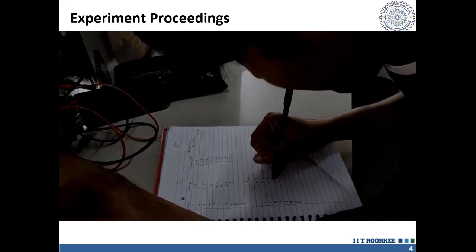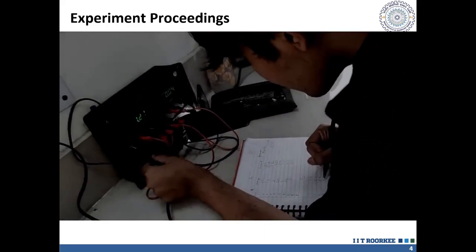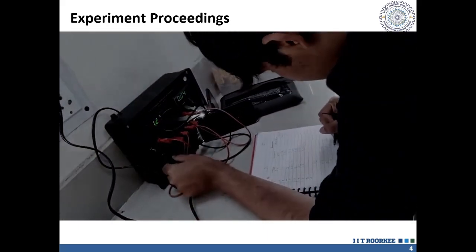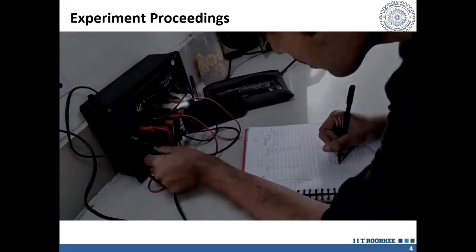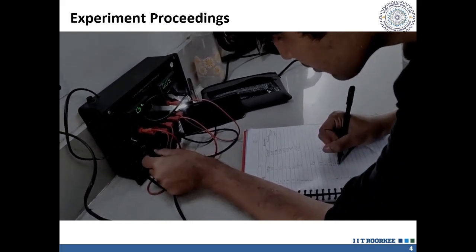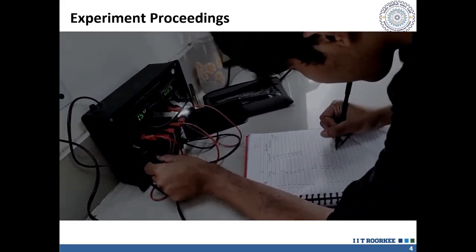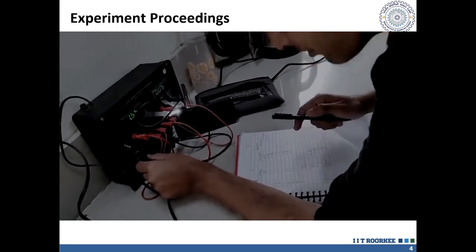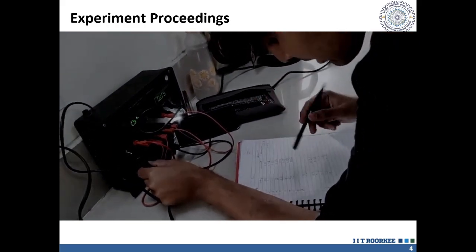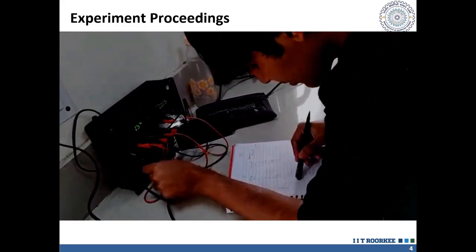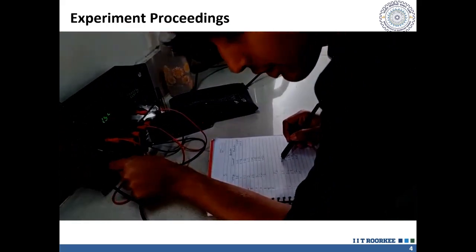Let's not judge the experiment yet, we'll keep performing it. At 1.5, we should get 0.05. So you can see the linear behavior over here, right? I'll keep heading on and taking the readings. You can guess the resistance to be almost around 30 kilo ohms.